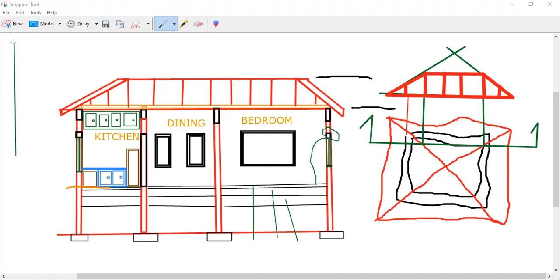So you draw this, then you could draw a line across here. This is the line for your ring beam. So that would be a start. You would estimate this line for the distance across the building here. You then offset this down to the distance from the ring beam to the finished floor, which in this case is 2,800. So you have that.